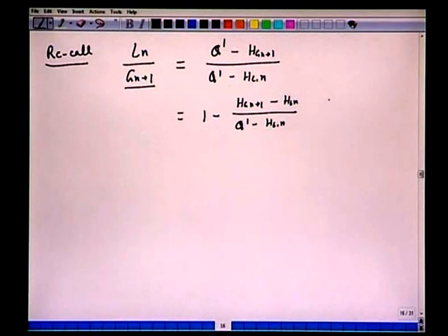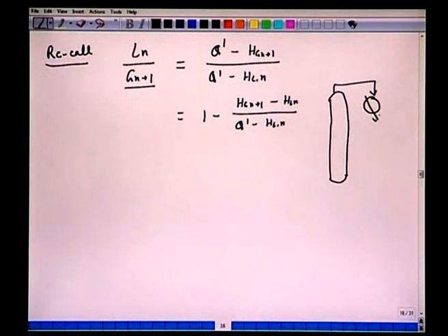So let's draw this schematic of this distillation column, and let's try to recall the situation: vapor coming here, we had condensation. Let's assume total condensation. We withdraw the product D, and the liquid goes back to the column as reflux.